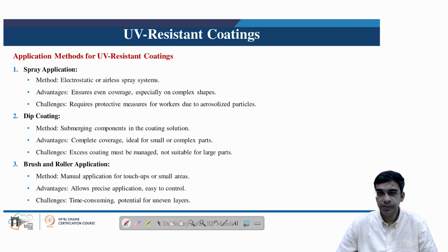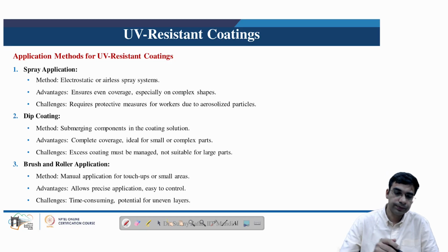areas, and this is popularly used for touch-up applications. The advantages of brush and roller include precision application and easy control. The challenges of brush and roller application are that it is time consuming, and this type of method is dependent on manual effort, so there may be generation of uneven layers.